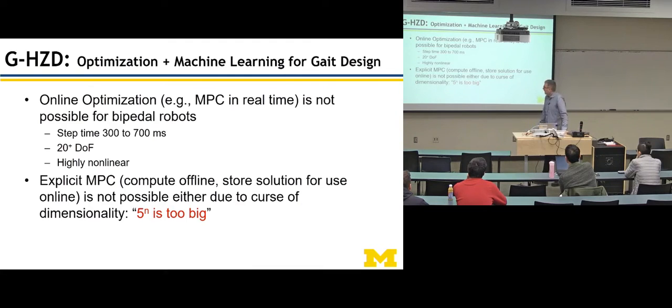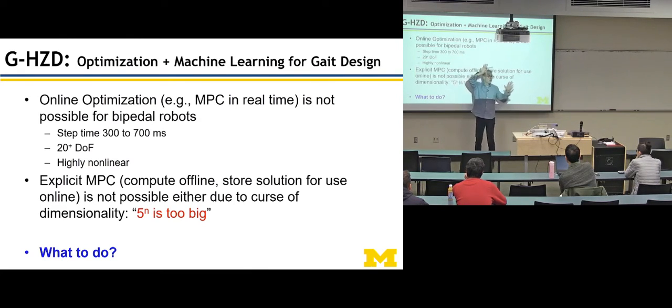Okay. And then what people were also doing is said, well, if you can't solve it in real time, do those calculations offline and then store it in a grid. And that's called explicit MPC, where you solve a whole bunch of things and then you just do table lookup online, okay? You just store it as a table. You get a value here, one here, you're here. You just do kind of a linear interpolation, okay? But the problem is you can't do it.